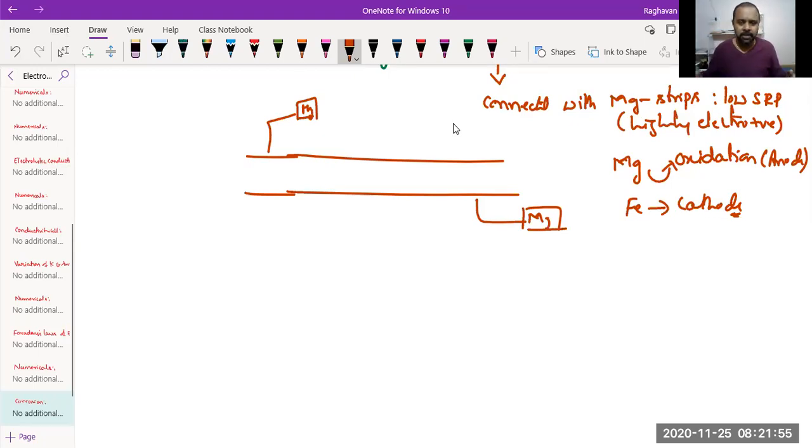They take wagons and heat them to red hot and pass steam on the surface. The steam will convert the surface iron to Fe3O4. Fe3O4 is quite stable and thus it can be protected. There is alloying. Chromium will be added to the iron to get stainless steel. Stainless steel is stainless, no corrosion. That's the meaning. No stain means no corrosion. Stainless steel contains chromium, which when present in the iron forms Cr2O3.